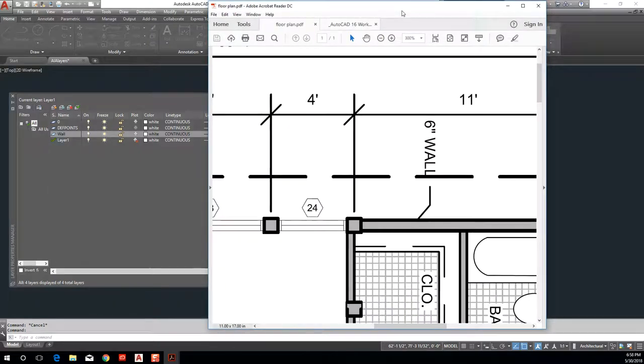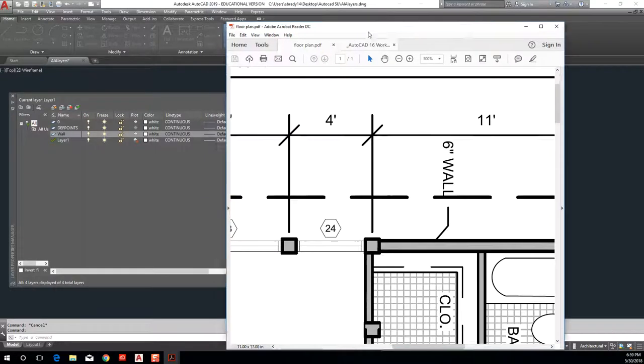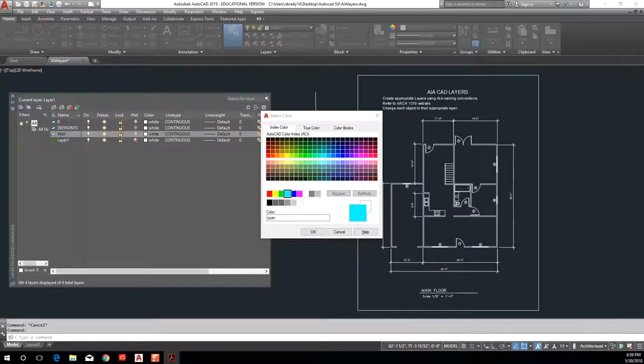Right? So I want to see a couple steps between pen weights so that your drawings, ooh, why is this so hard to pull over? There we go. So that I see a step between the pen weights on your drawings when they're printed, okay? So that's kind of what I'm looking for. And I think in industry, that's what people are going to be looking for as well, right?